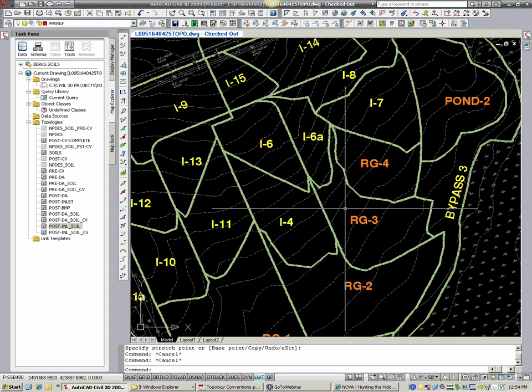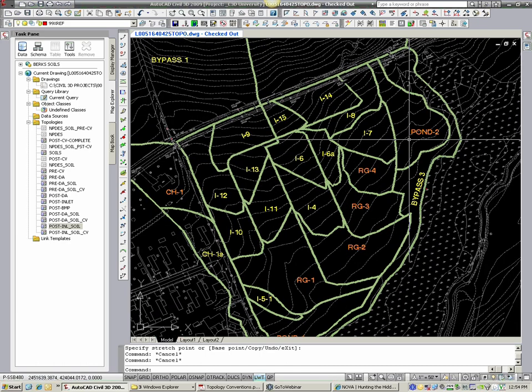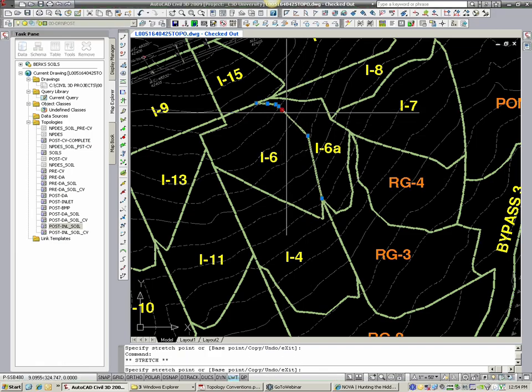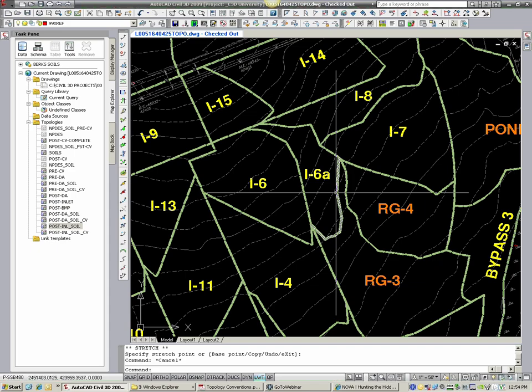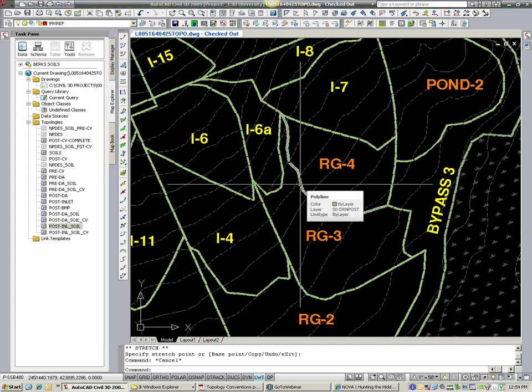Well, by moving those lines, I updated, and it depends, if you're updating a line that's the division between pond 1 and pond 2. But if it is like this line here, if I move this line, I updated a bunch of things. I just updated 3 topology maps. I updated my BMPs, what flows to my BMPs, what flows to my inlets, both inlets, because they both change, and what flows in between pond 1 and pond 2. So you think, oh, is it totally automatic?